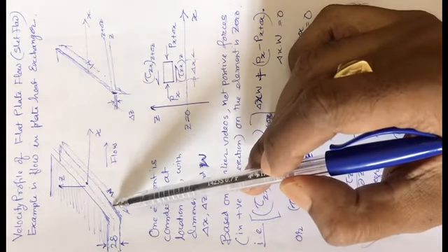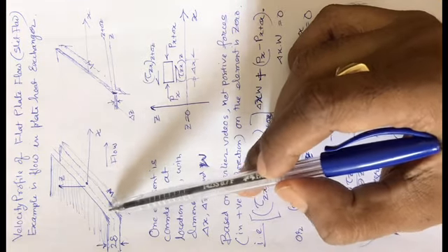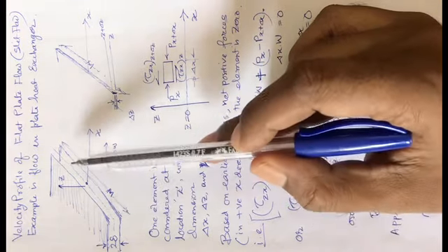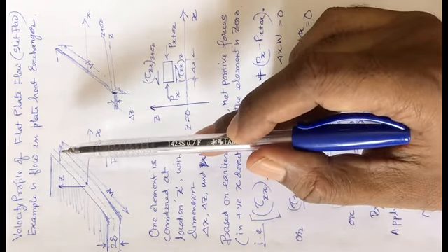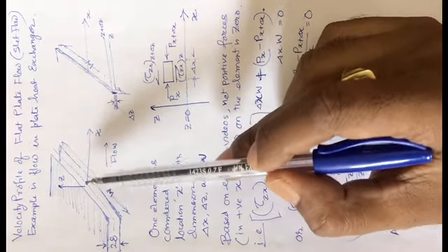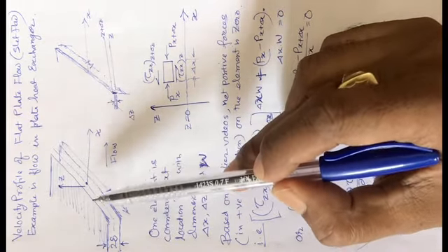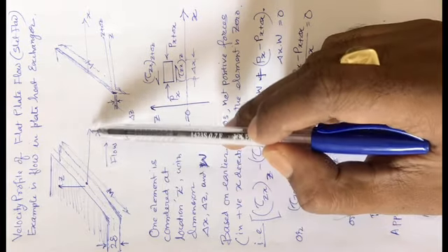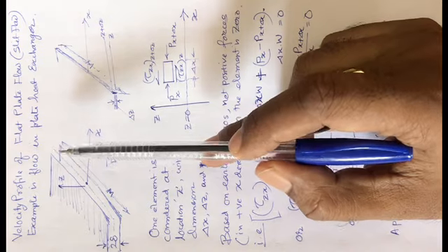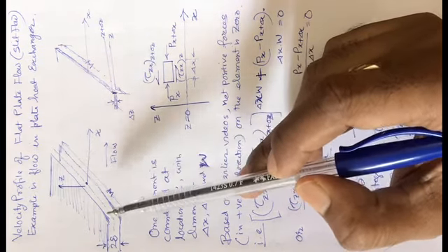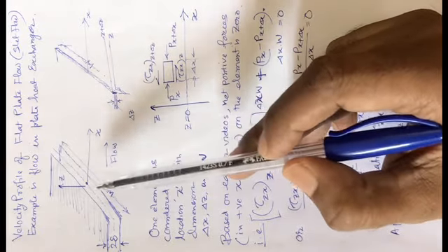One plate is being placed above another with some spacing provision, or some spacer, for maintaining the spacing, and in case of a plate heat exchanger you know that gaskets are used. So with some support that gap is maintained, then fluid is made to flow from left to right because of pressure.